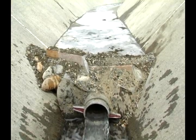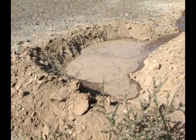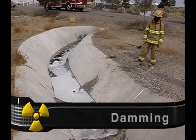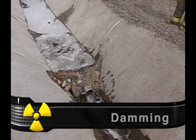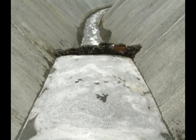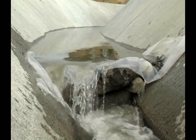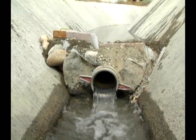Important spill control techniques also include damming and retaining the hazardous product. Damming involves constructing a barrier across a waterway to stop or control product flow. Think of damming as going across, where diking goes around. Dam types include the overflow dam and the underflow dam.